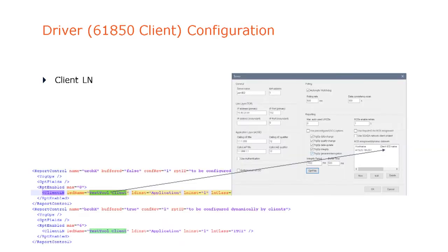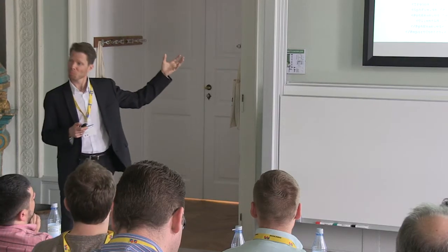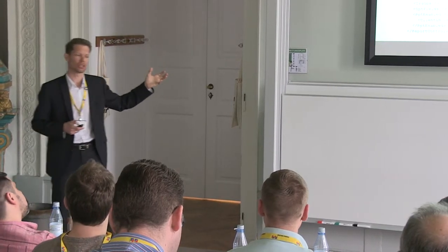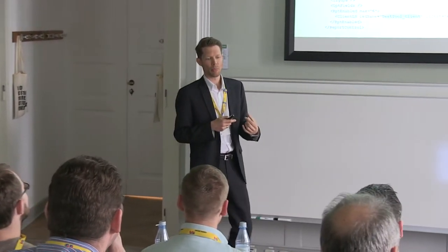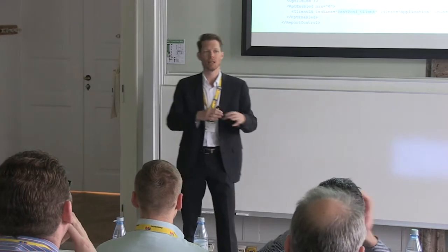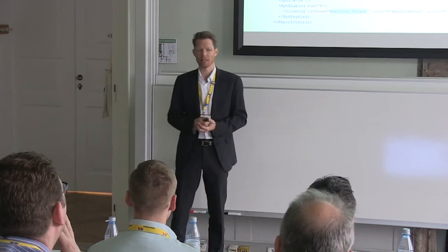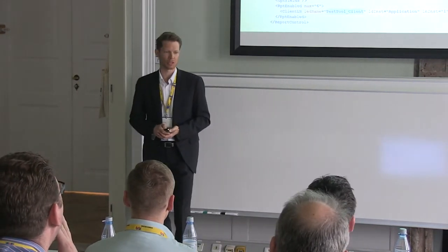As I said, there is one thing that is completely possible with the SCD, the driver configuration. There is something which was already invented with edition 1 of 61850, but in edition 2 it became kind of mandatory or very popular. You can now use the client logical node, which gives a lot of information, for instance, to automatically configure all the reporting that is related to the 61850 client.